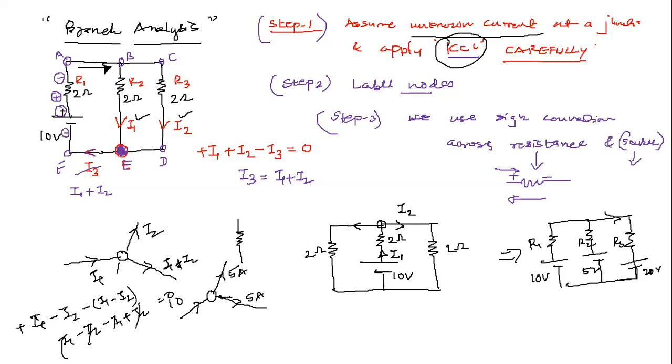So if you put positive here, what will happen? You are not going to get 0. But we don't do this every time, no? When we apply KCL, we don't actually do this. What we assume is, let us assume this is a 10 ampere current, 5 ampere is through this R3, and the remaining 10 minus 5 will flow from this. We directly do that, right?